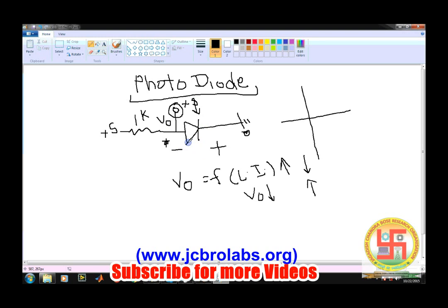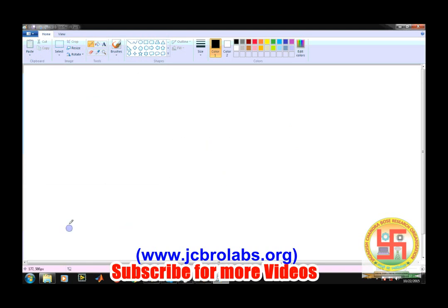We can create an IR sensor based on the combination of these, and the circuit diagram for that is very easy. We connect an LED. The LED needs to be in forward bias. Again, I'm making the same mistake with reverse bias. So we have connected an LED. This is 5 volt, this is ground, and this is a variable resistance. By applying a variable resistance, we can change the intensity of this IR LED. So this is the circuit diagram for the transmitter.